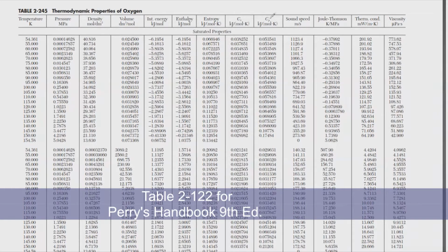There are also the specific heat capacities here, the Cv and Cp. Now we'll be using Cp since we're assuming that there's a constant pressure in the system. The constant volume is different since there's no constant volume but a continuum. What we need to do here is to find the properties that must be used in evaluating the Reynolds number. That is the density and the viscosity.